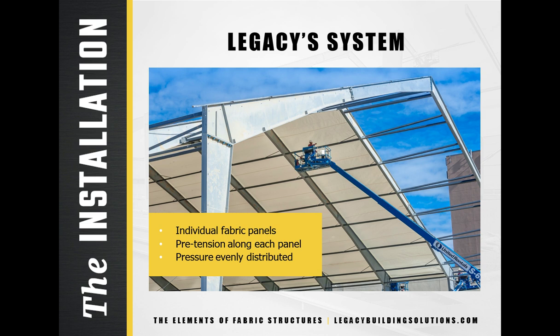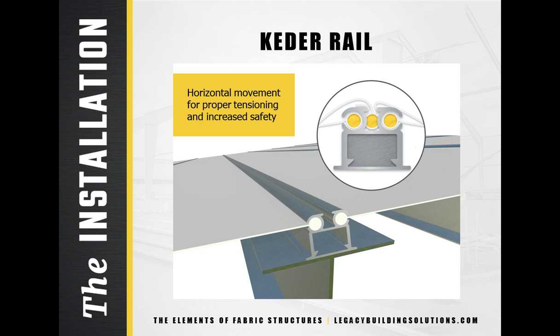There is also greater vertical, or up-and-over, tensioning because the fabric is tensioned in a straight line, not around any radiuses. This increases the system's longevity, especially in cases of severe weather. In this system, a Keder rail slides horizontally on the top flange of the frame, eliminating the need to detach or flex frames during the fabric installation process. The extrusion is attached to the frame with half-inch bolts, eliminating the challenges of the tek screw while allowing for the very important horizontal tensioning after the frame is fully secured into place.